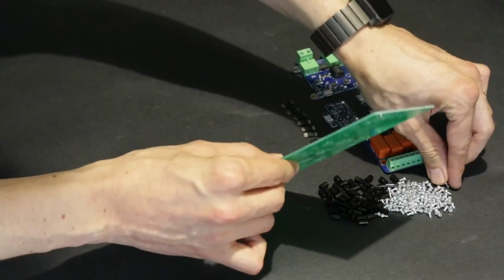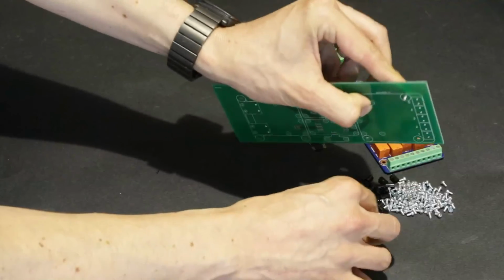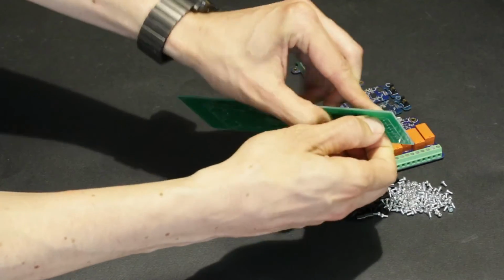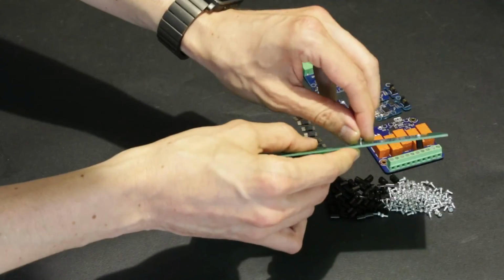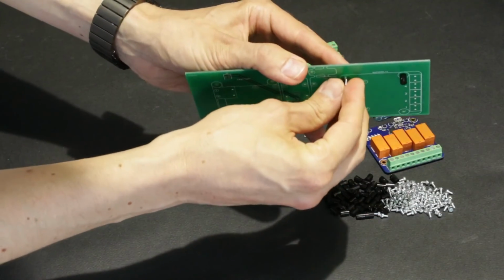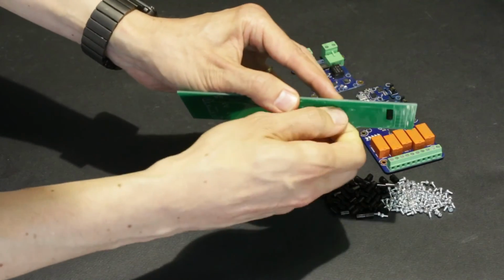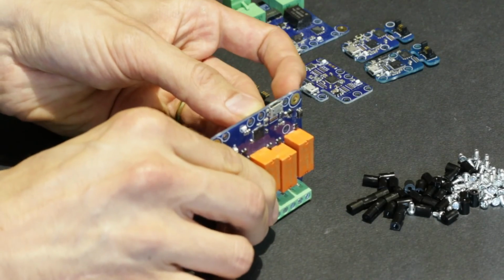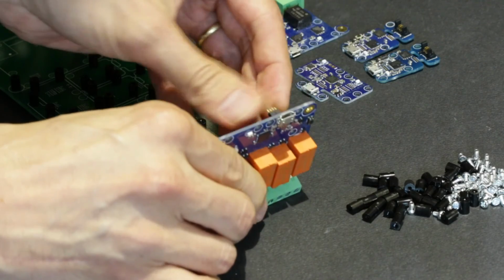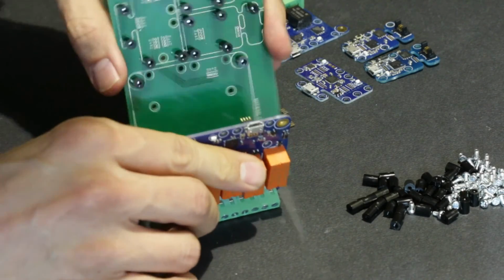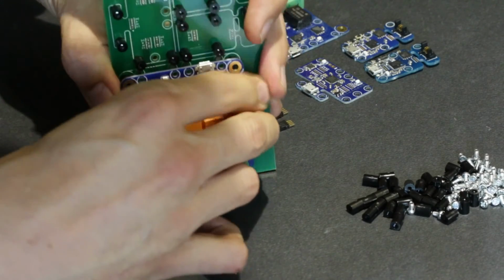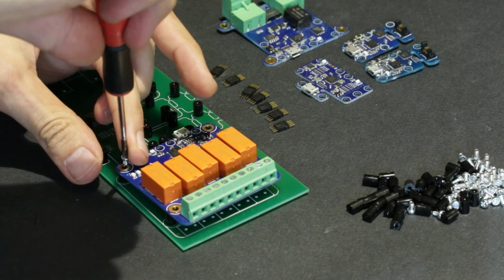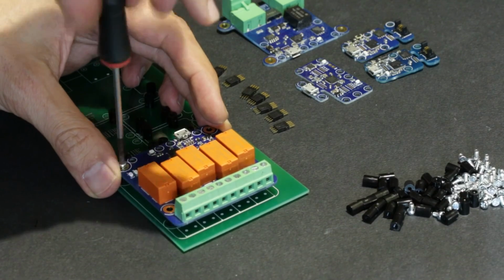Now, to assemble the PCB and the Yoctopuce devices, the best way is first to put all the spacers that will hold together the PCB and the devices. So it's simple screws. These are the screws and spacers sold under the name Fix 2.5 on the Yoctopuce shop. And then you will be able to put the board-to-board connector that will connect together the PCB and the device. So first connect the board-to-board into the device, hold it vertically, and come with the PCB so that both fit together. If you then screw the device to the PCB, the connector will not move anymore.